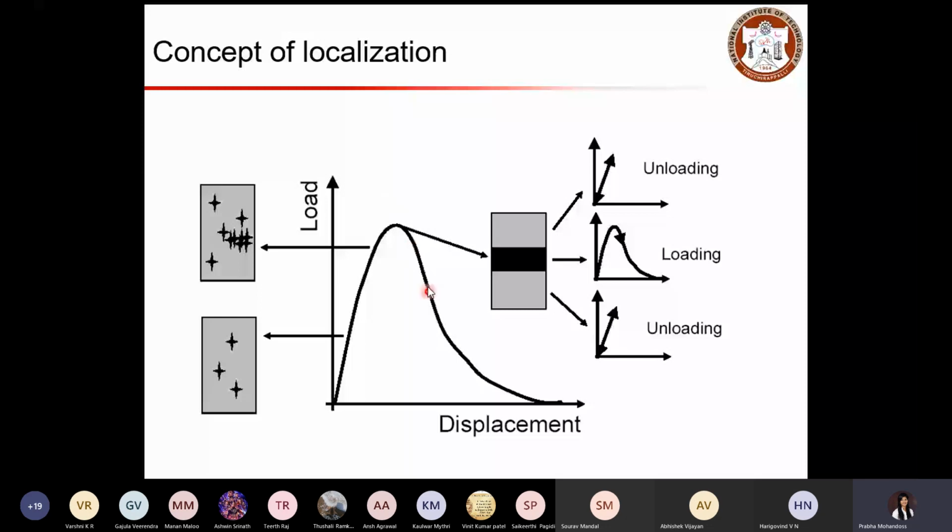So here are illustrations to understand how the loading cases affect the concrete stress-strain behavior. As I said, this is the pre-peak region. When you are in the pre-peak region and you unload, your member can come back to its original condition because it is in the elastic stage. But in this case, your member has reached its peak, the ultimate condition is attained, and then it starts failing. So you will get the stress-strain response in this region something like this.